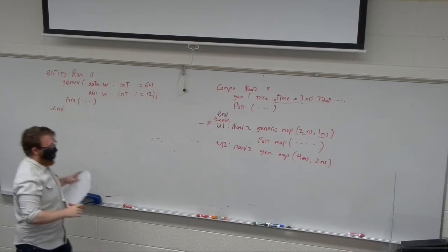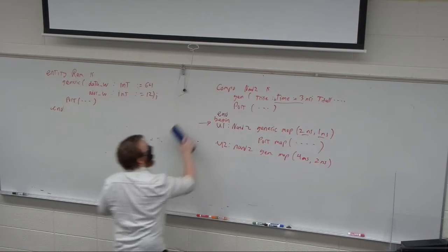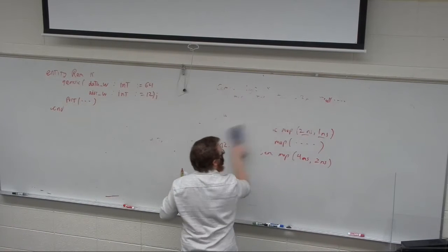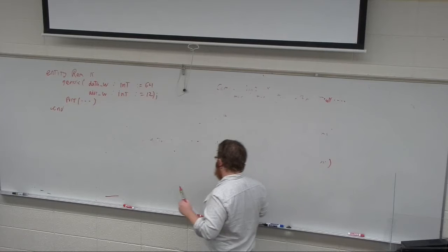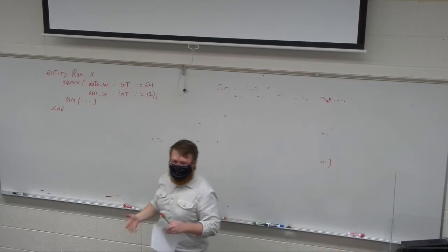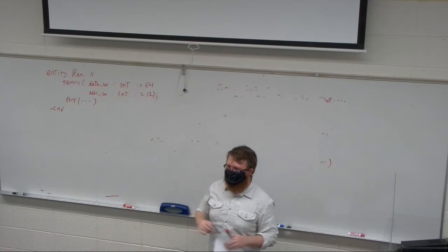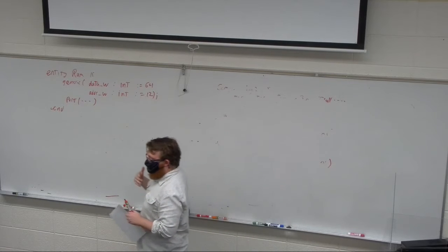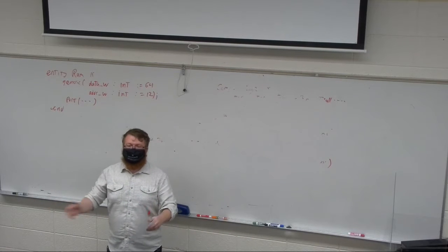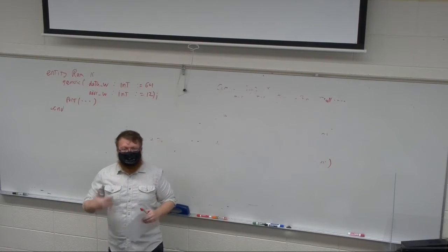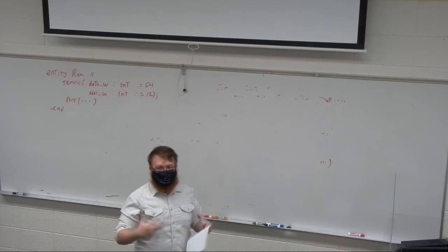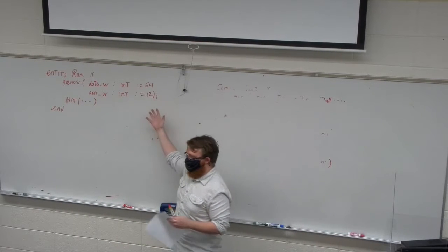Let's stop there for a second. We used the IP core when we created our ROM and our RAM: ROM for SPI, RAM for I2C. But if we want to create one of our own that isn't using an IP core, we can assume we're going to create lots of these and use them all the time.